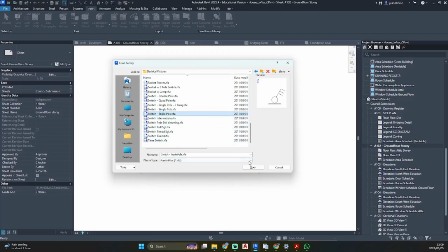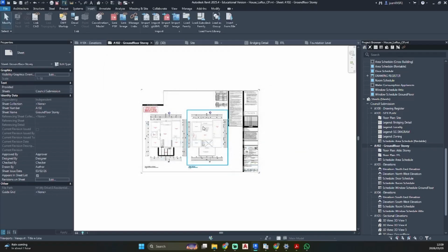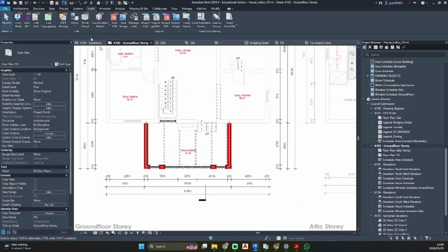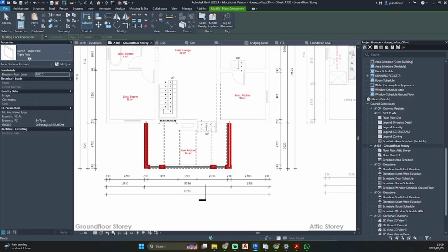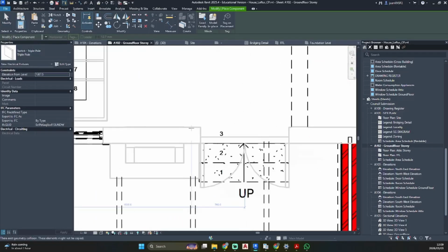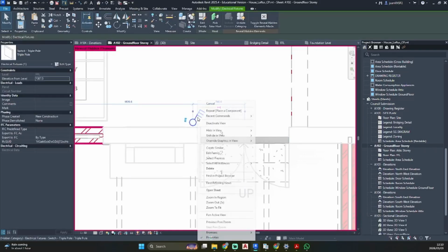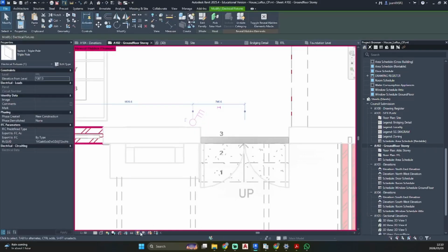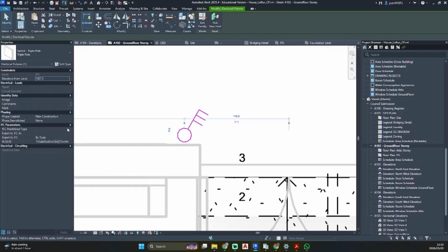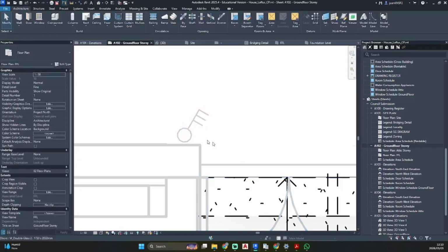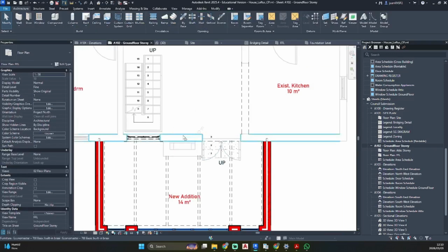This is what I want. And in here, I'm gonna go and add my switch. There is a switch over here. And since it's not visible, I need to go and check. Okay, so there is an existing switch over here that connects to a light in the braai and a chandelier over here. But now we need to add lighting in here.